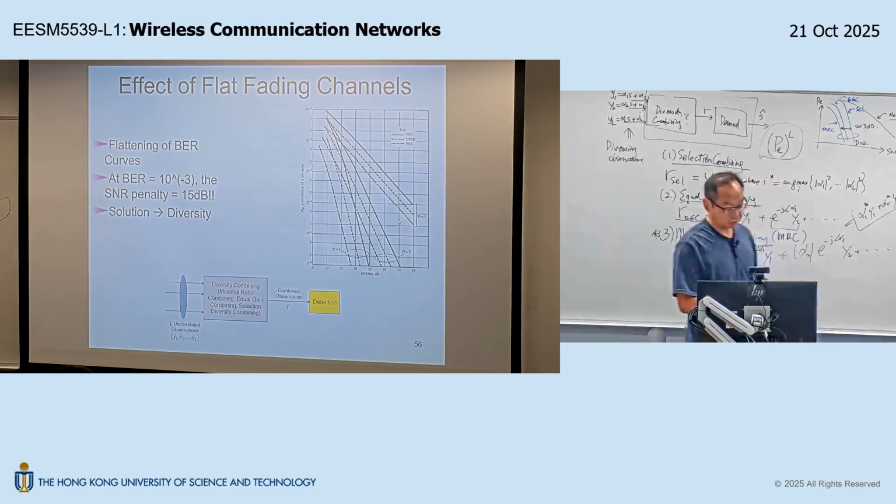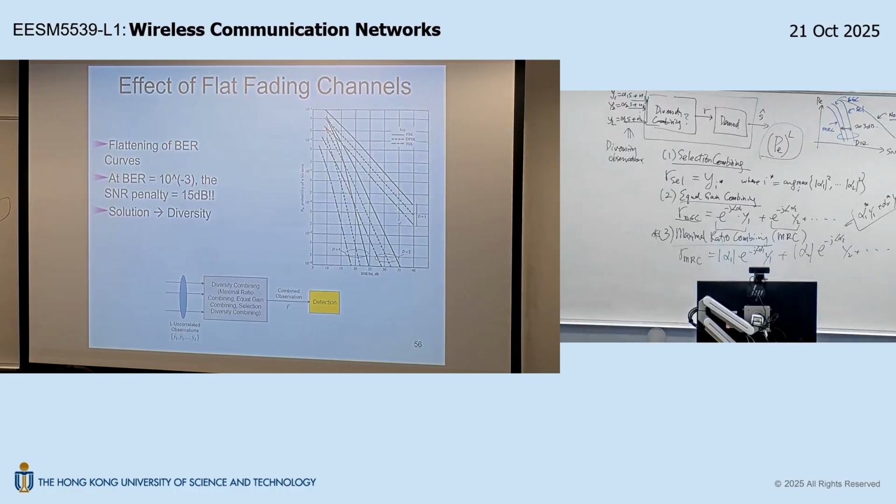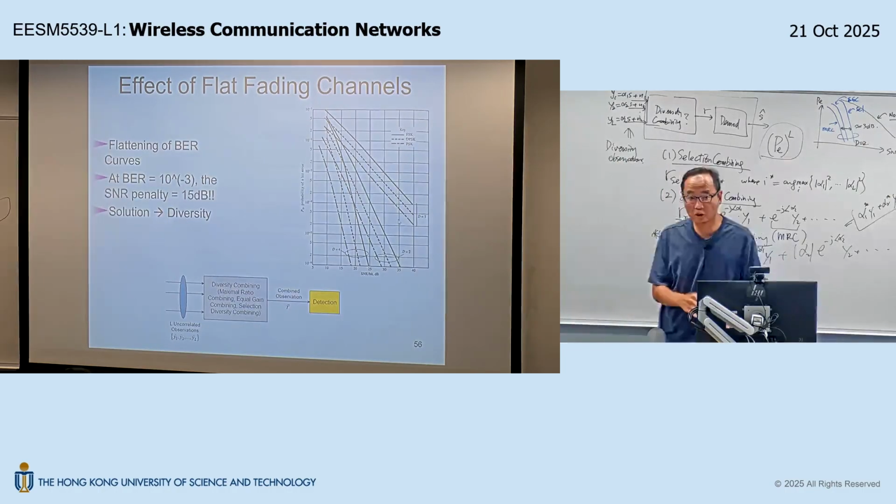So of course, at that time, the chipset solution only had 2 receive diversity. That was sufficient, because at that time this is the cost unit, right? So you don't want to sell the solution too expensive. Therefore, you cut corners by partitioning the preamble into 2 halves, and you already suffer a 3 dB penalty. So you don't want to further partition this, and you don't want to increase the cost unit by too much. So at the end, you end up with 2 receive antennas. That will pretty much give you the optimal trade-off.